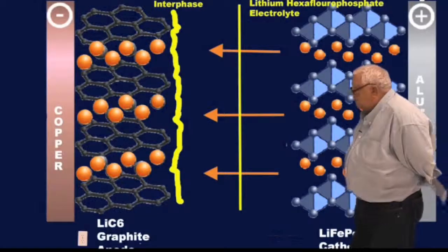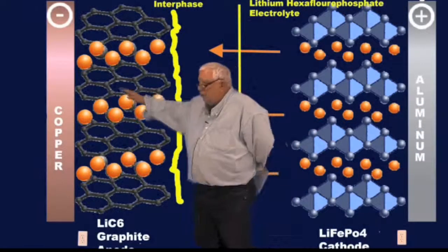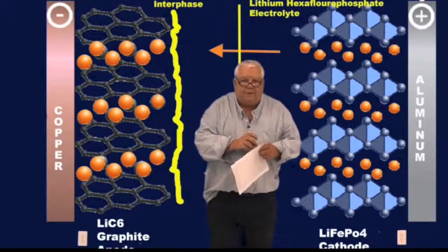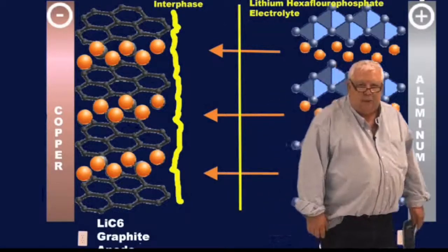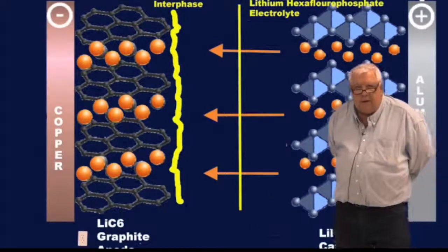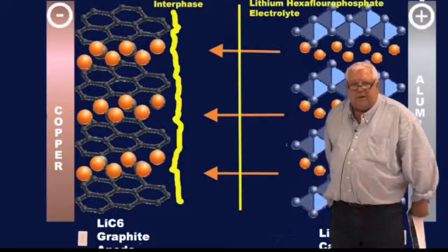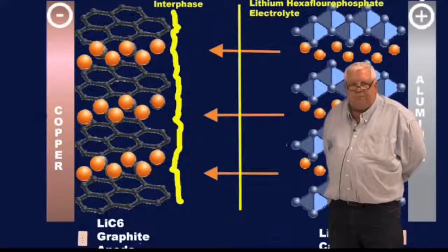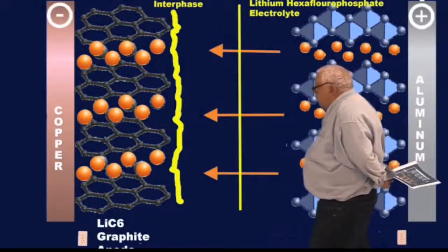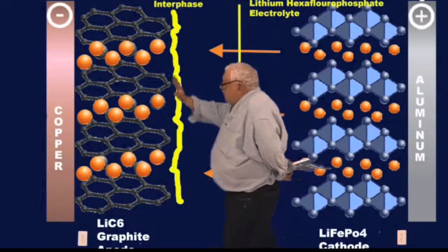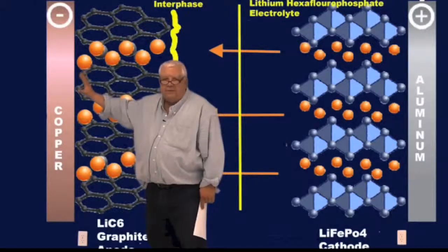The process of intercalation of lithium ions into the carbon causes the lattice to expand mechanically, and it fractures in some cases. Intercalation, it expands. Deintercalation, it shrinks back, and this wears out our carbon, and it breaks into pieces. The SEI layer kind of functions to hold that wall of crumbling bricks together in place and extends the life